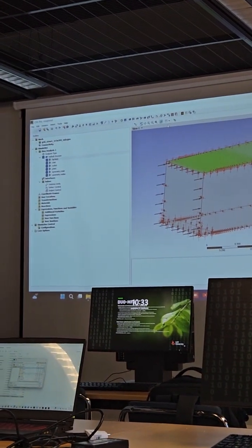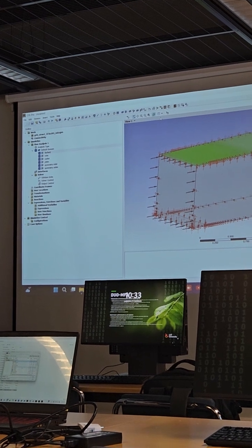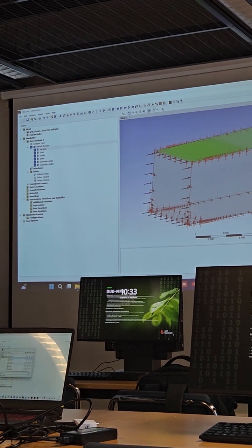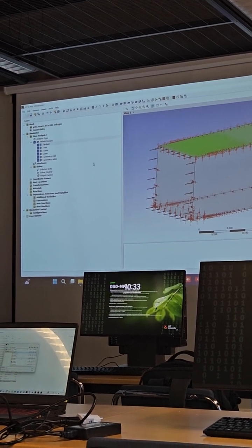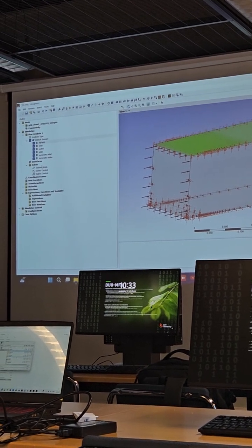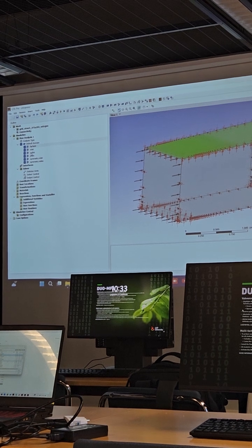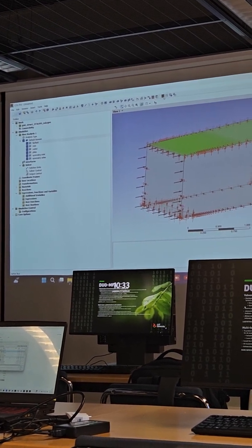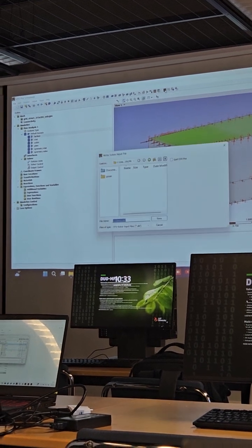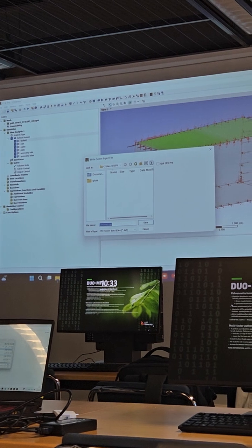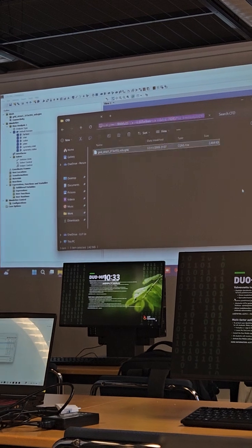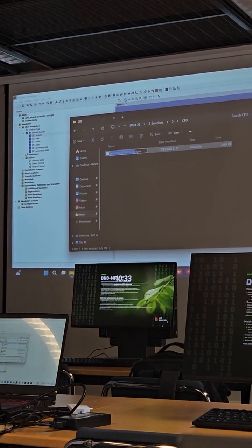So in order to create a file that is compatible with Fluent, you should create a def file. The def file stands for definition file. We don't need actually to set all the other information in CFX as it will not be transferred to Fluent. So we can just push that Define Run on the top, and then you can see this def file. I call it with the same name of the mesh.